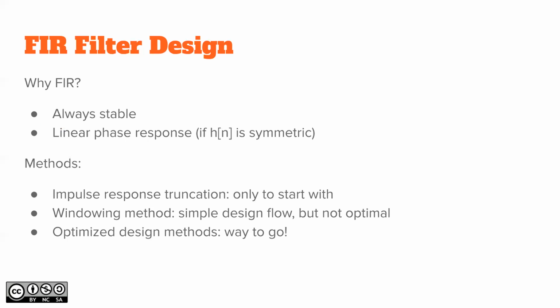Now, three methods, and I will go just for fun with the impulse response truncation. That's basically the simplest way of measuring a system and defining the transfer function. But anyways, there are more sophisticated methods to do this system characterization based on the same measurements. But it's a nice way to start.